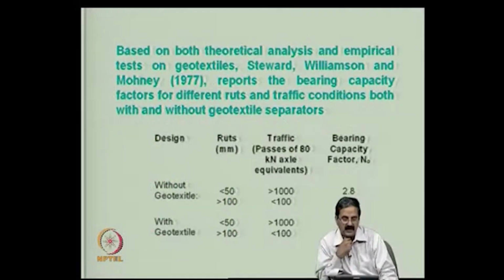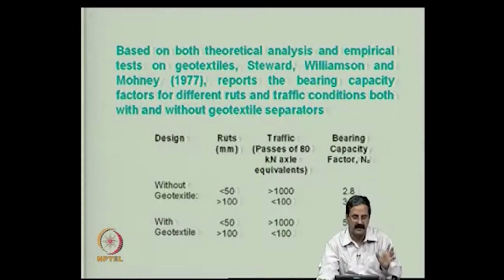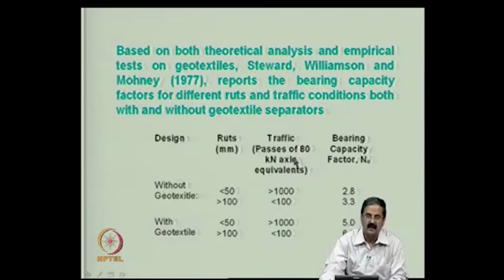So, there are some more studies that people have done, and people did a lot of field studies as well on clays. If the traffic, we know the standard load, in the Indian standard code, it is 8 tons, 8.16, so we call it 8 tons, okay, which is 80 kilonewtons actually, and it is the same even in the US code.